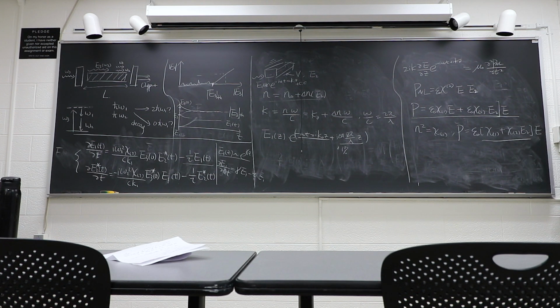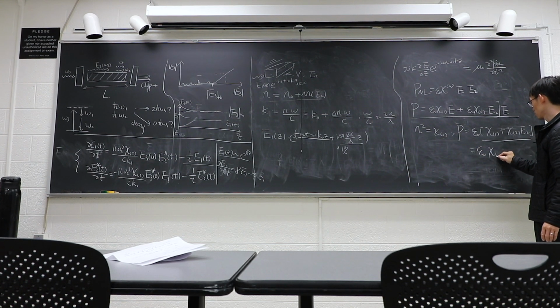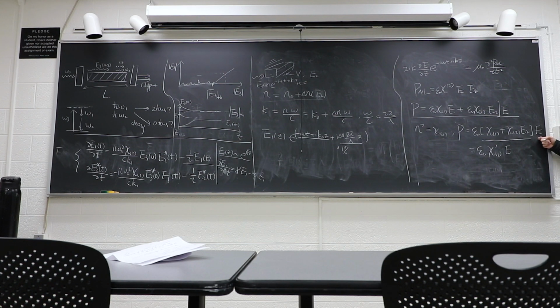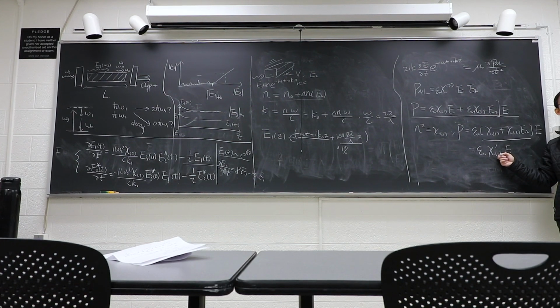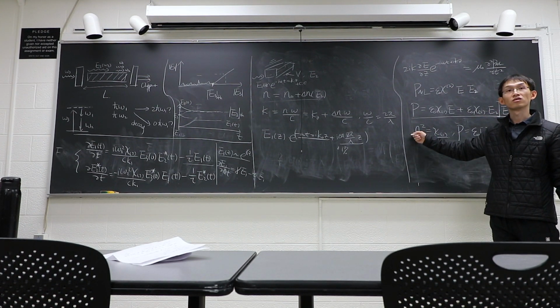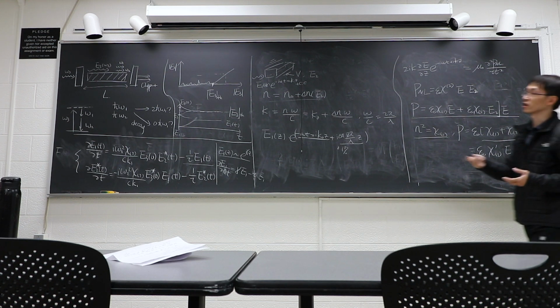What it looks like is that your E2, your field, or your voltage applied to your waveguide, changes your chi1 a little bit, right? And that chi1 change changes your refractive index. So this is actually a microscopic view of how this effect happens.